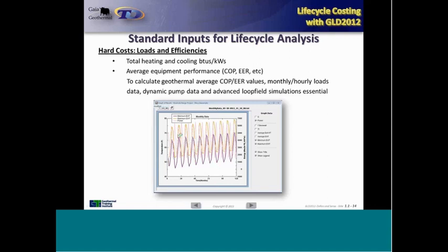The yellow ones give us our maximum temperatures over 10 years. And then we have this hard to see pink line, which is our predicted kilowatt hour consumption for each month of the year, or month over many years. So this is the kind of data that we really like to see to fine-tune our COP and EER analysis to really show the most benefit that geothermal can provide.